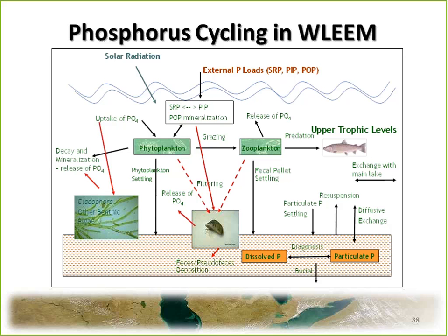So the biological part of the Western Lake Erie ecological model has these components. It's ultimately all about phytoplankton growth and cladophora growth. But to get there, you have to understand the cycling of nutrients and solids, the loads that are coming in externally, how they're filtered by invasive clams, and how they move in and out of the sediment bed, depending on oxic and anoxic conditions.